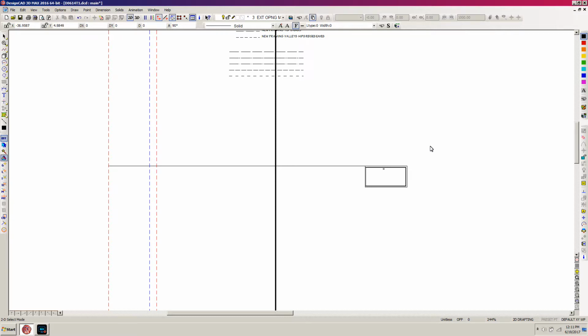So now I'm going to select this door, and I need to locate a handle to this lower left, to the bottom edge of the door at this line joins it. So I'm going to go over here to set selection handles and click on that. Then I'm going to go over here near this corner of the door where I want the handle and right click to it, and it gravity snaps to it. And I'll probably go ahead and get rid of the orthogonal mode. And now I'm going to either hit enter or my scroll button on the mouse. And you can see it set the handle there.